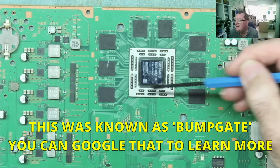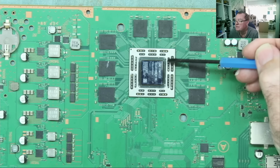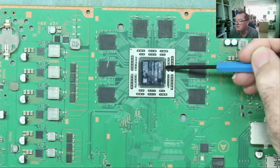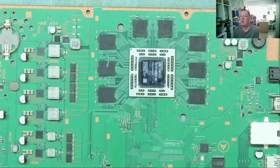So by heating it, but not to the point where you melt those and then let it cool down, you may find effectively this flexes a little bit and the thing will work. But this only applied to NVIDIA chips of a certain era. Okay, it's not a general technique, and often if it did work, it wouldn't work for very long because you haven't fixed the problem yet.